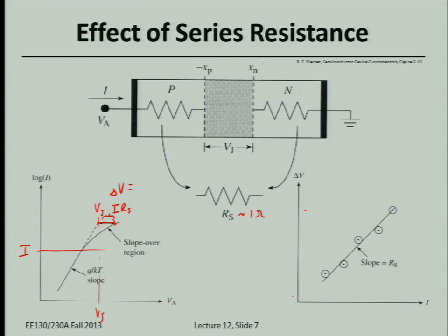Yeah, what happens probably is that the dopants on each side will start to diffuse also, so you won't get a nice, perfectly abrupt junction. You might start to get a linearly graded junction. It's because of the time scale. When we anneal, we try to anneal very quickly, in seconds or milliseconds. Here, the Joule heating process to heat up and cool down is much slower than that. So things will diffuse, and you won't have precise control over the temperature profile in your diode, because you have conduction. You're not going to get uniform heating.